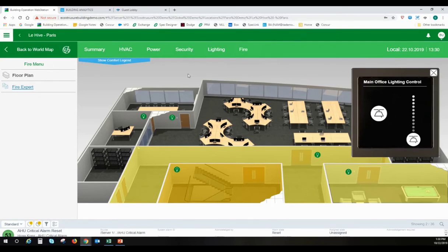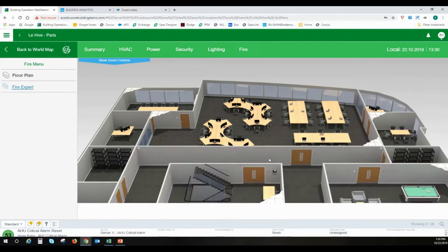And then the fire, we get a lot of questions on fire integration. And the thing I always say, there's really about 3 ways to tie into fire. We're not UL approved for life safety, though we do have a smoke control rated system. So we are UL 864. A lot of the larger manufacturers are and have that type of integration, and that would be where we would do the smoke control, evacuation, in addition to working with the fire alarm to get alarms per floor typically or per zone. That's one type of integration.